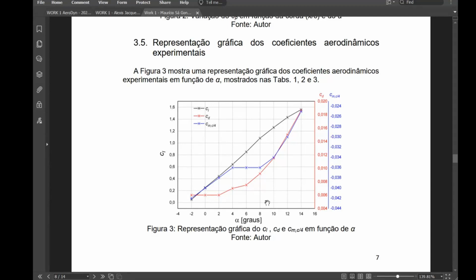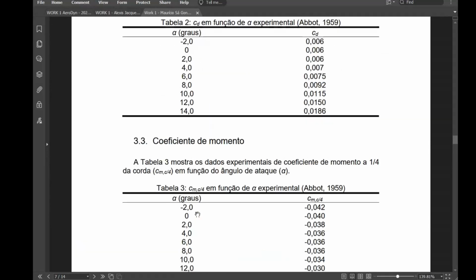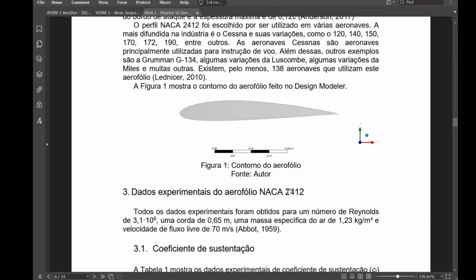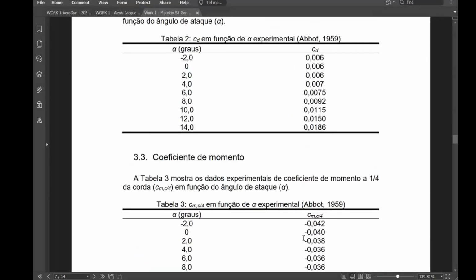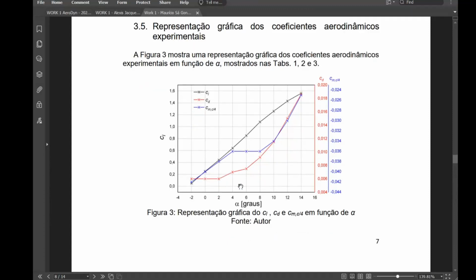Okay, so that's it. Let's see. Yeah, so this -2 is close to zero lift angle of attack, -2. Since airfoil is not symmetric, I think it's 5-digit airfoil. Let's see. No, 4-digit airfoil, but it's cambered airfoil, not symmetric. So it's displaced from origin of coordinate. It goes upper. And at zero angle of attack, we have some small value of lift coefficient.